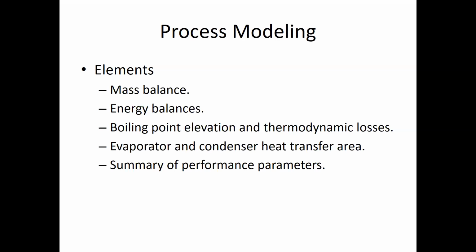A part of the vapor is being lost. And that depends on how good and experienced the person is who operates the venting system, so that he makes sure that he only gets rid of the carbon dioxide and non-condensable gases and does not leave the vapor to be lost. So these are the kind of losses that you expect in a system like this.